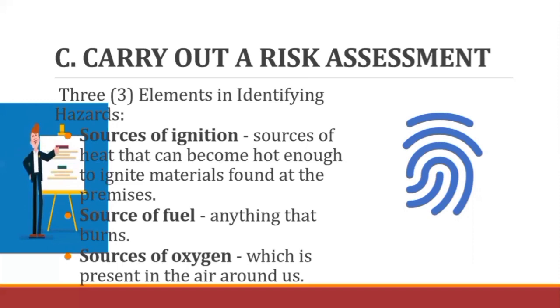The only thing we can do is to have a measure to control the temperature, right? To control the temperature, and be careful with the backdraft again. When there is a fire, there is already the threat that a backdraft may occur. Then you have to control the passage of oxygen.